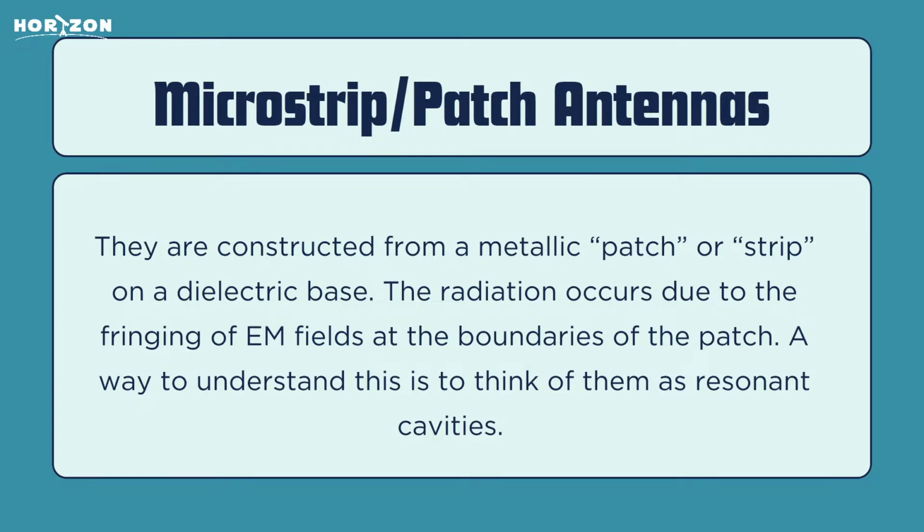The transmission lines that we see around us, the wires that we have, or the USB cables that we're using, they all have their own intrinsic capacitance, inductance, and resistance. And as we have learned in our 11th grade, an RLC circuit will resonate. It will release electromagnetic radiation, and it will lose its energy. So in a similar way, this will also behave like an RLC circuit, radiating out energy in the form of EM waves, maybe radio waves or microwaves.